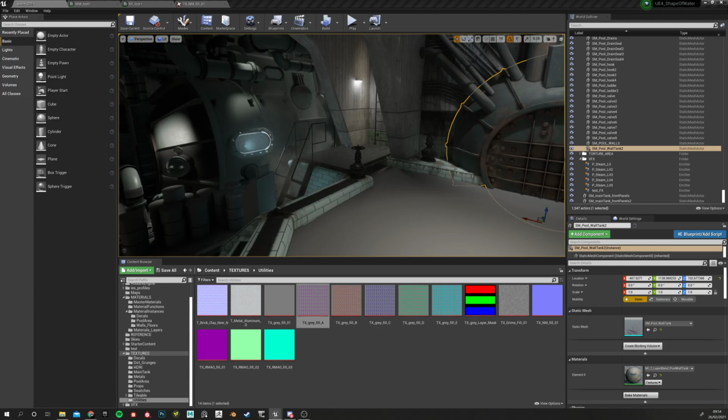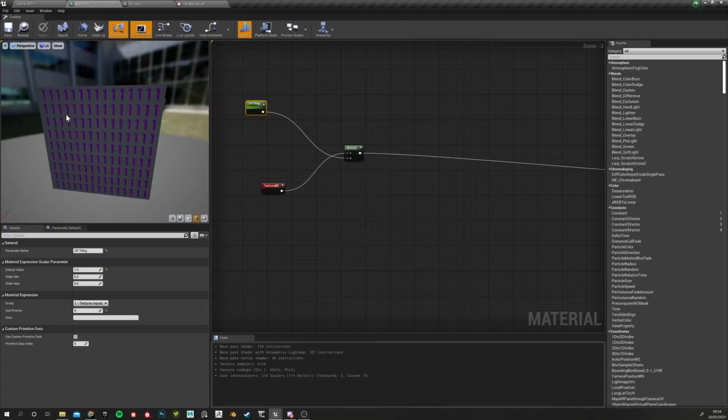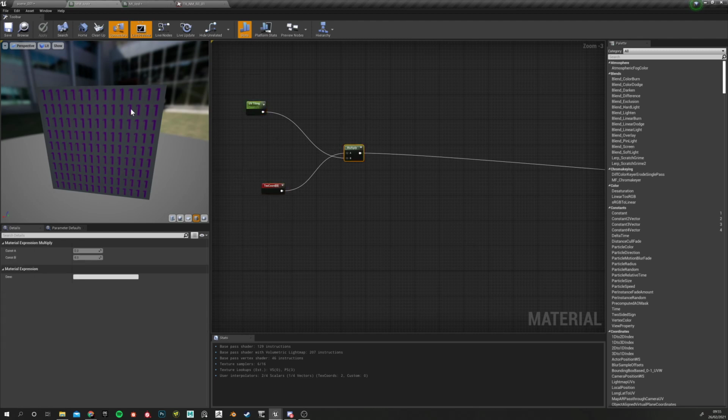That functionality would be to actually offset the UVs. And for the offsetting of the UVs, you have to add something to it, because if you think about it, when you have UVs, you go 0 to 1 here, and you put another UV here, that will be the 1 to 1, the 2 to 2, the 3 to 3, and it will go up as well if you want, in Maya. So you have to multiply the UVs by a number to change the scale.